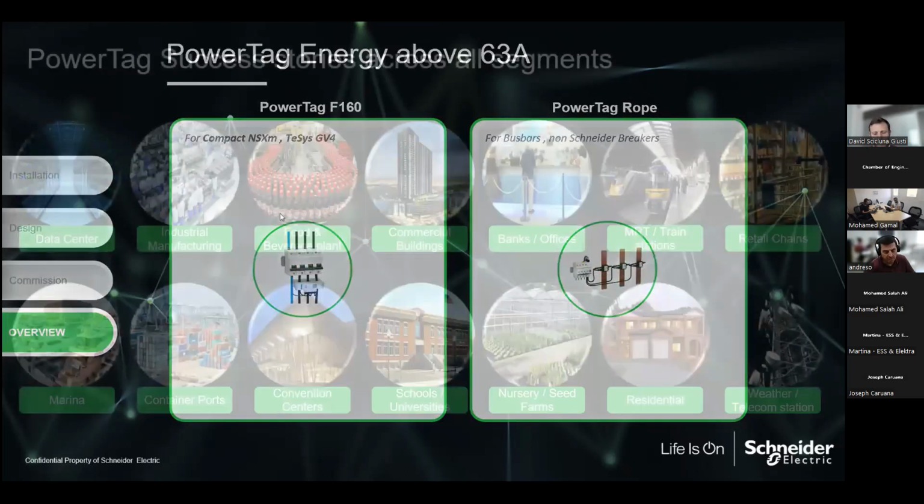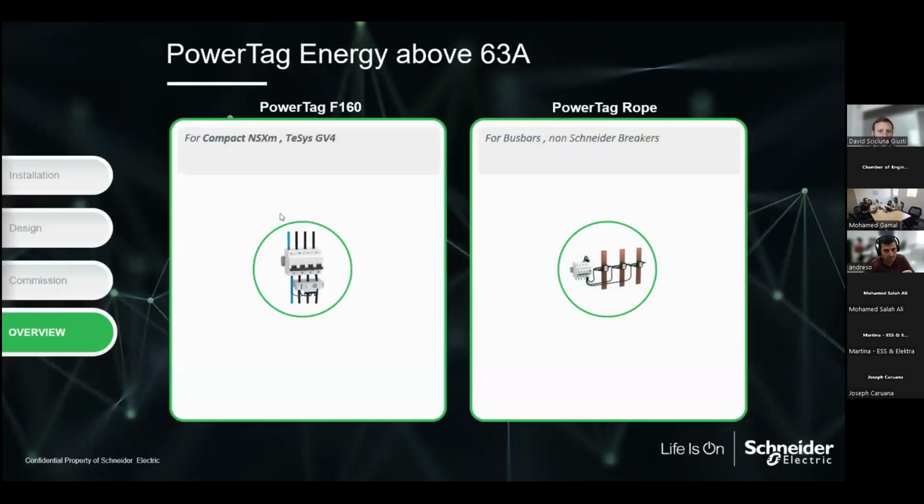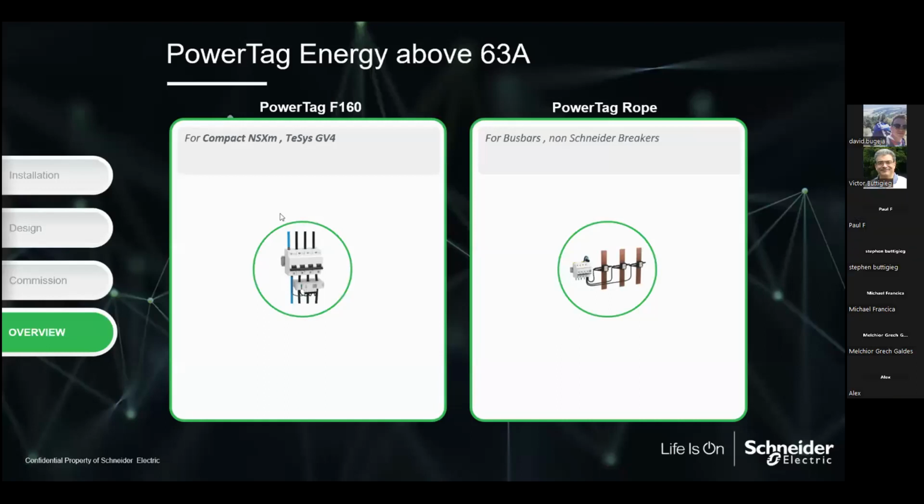Is there a limitation on the lower side of the current? Good question. The minimum current that the PowerTag could measure, right? I tested and validated it can read about 0.1 ampere or 0.2 ampere, up to the range of 1 ampere you can read.